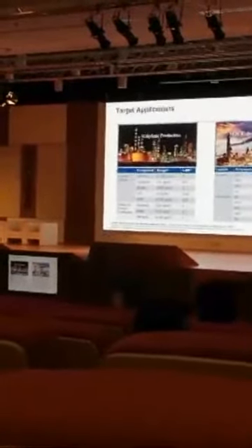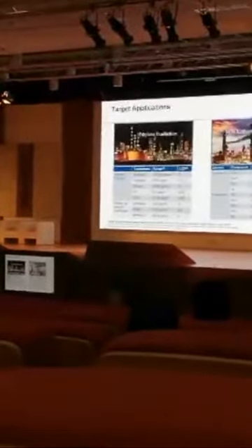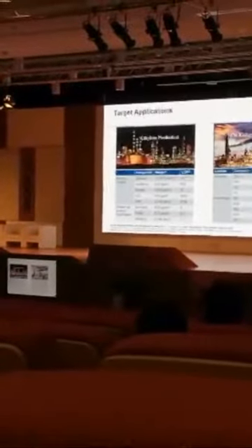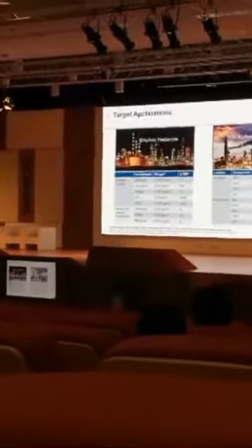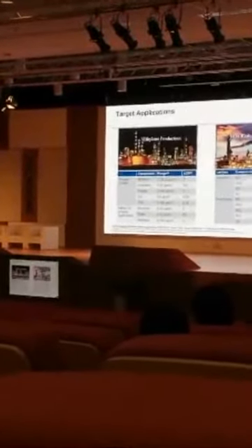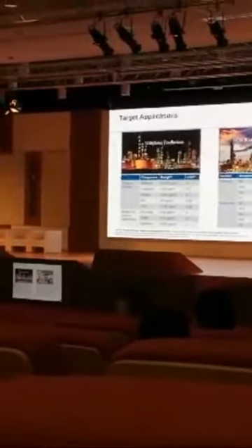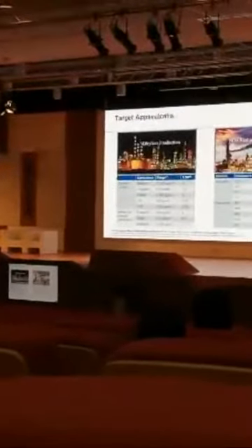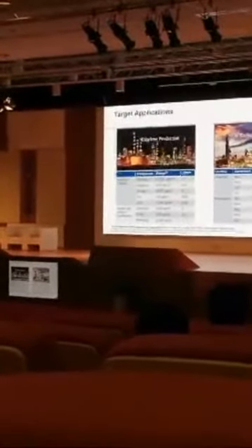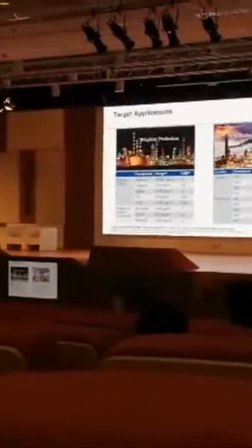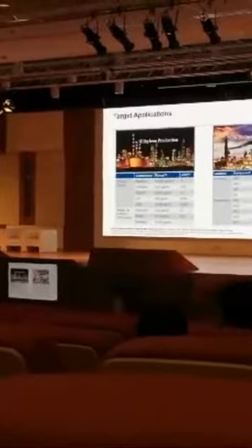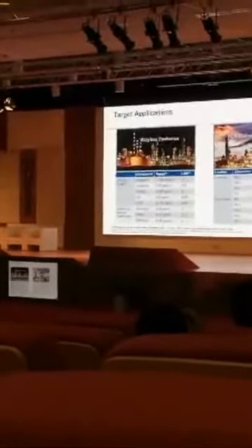Also, during custody transfer for ethylene, you may want to have these kinds of measurements. So you can measure methane, acetylene, CO2, CO. These are some of the impurities that you would see. And additionally, if you want measurements like ammonia, water, and methylene, that can also be done. The advantage is that you don't really need multiple analyzers. As I said earlier, the quantum cascade laser can do up to 12 measurements using a single gas analyzer. Okay. The next application is ammonia injection, normally to reduce the NOx concentration in the stack.